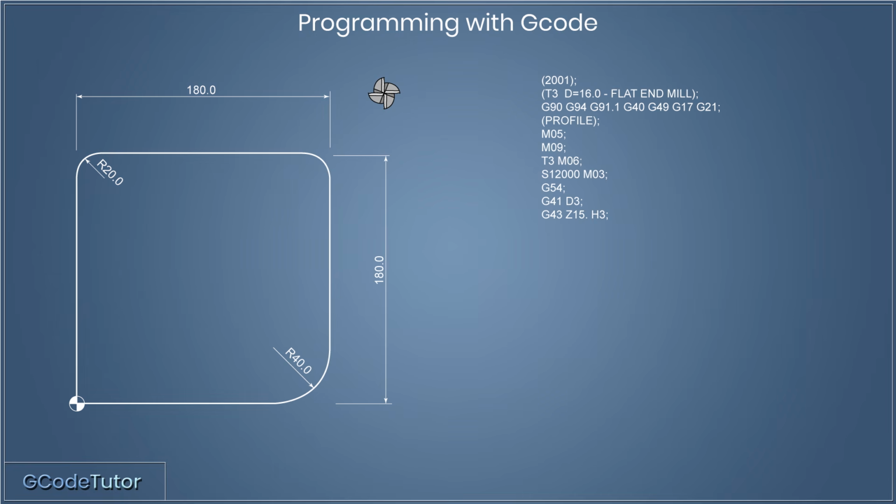G43 is similar. G43 tells the machine to call upon the tool length offset, so the machine knows exactly the tool length that we are using. We can set this on this line as well by using a Z value, so we can tell it that the tool is 15 millimeters long, or we can call that information from the tool table using an H value. So H3 would call that information from the tool table. So H calls for the tool length or the tool height from the machine controls, and D calls the tool diameter. M08, or simply M8, turns on our coolant.